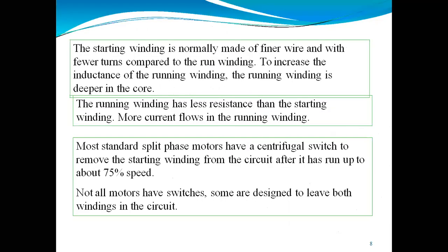So here, the starting winding is normally made up of finer wire and with fewer turns. Because we are saying winding, we can make it by using the inductor which will have the turns. So here we can say it will have fewer turns as compared to the run winding. And to increase the inductance, the running winding is deeper in the core. And as the running winding has less resistance as compared to the starting winding, a greater amount of current will flow in the running winding as compared to the starting winding.